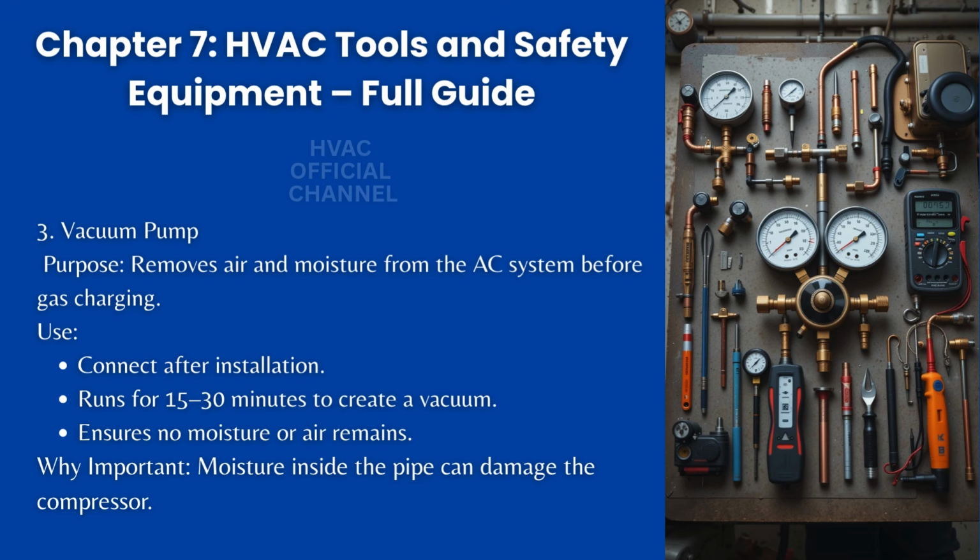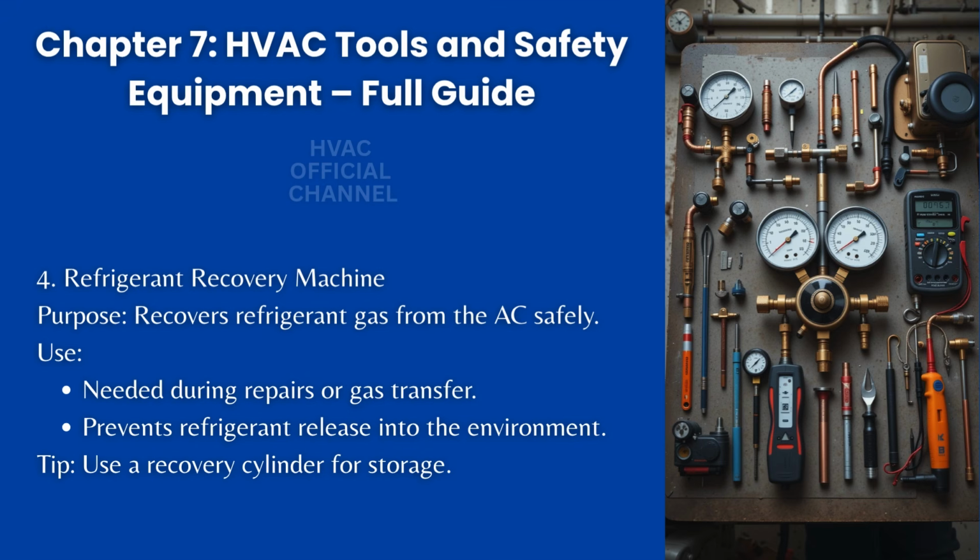Why important? Moisture inside the pipe can damage the compressor. 4. Refrigerant recovery machine. Purpose: recovers refrigerant gas from the AC safely. Use: needed during repairs or gas transfer. Prevents refrigerant release into the environment. Tip: use a recovery cylinder for storage.